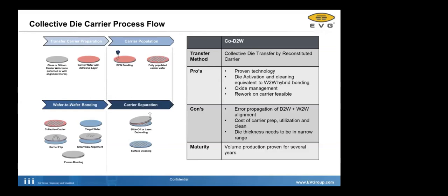The cost of the carrier preparation is definitely one of the drawbacks of this process technology. However, it solves a lot of integration process problems that you would have placing very small, typically very small dies in the compound semiconductor in a direct placement way.